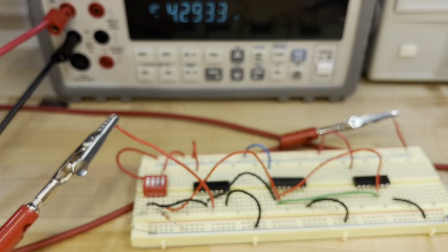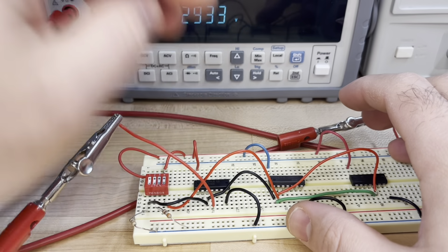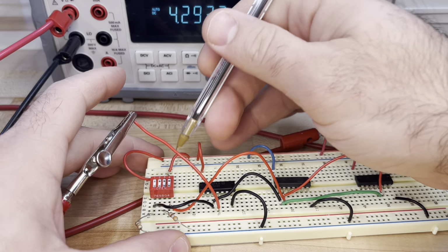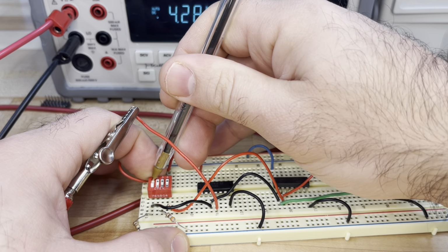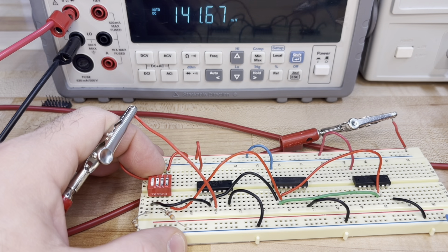Next, what does it mean to have 1? So we're going to put the output the same, but we're going to press the switch to make it 1 or on. Here we go. So right now we have 141 millivolt. We need to write that on the table. And in the same way, we're going to get the results for the OR gate and the AND gate.